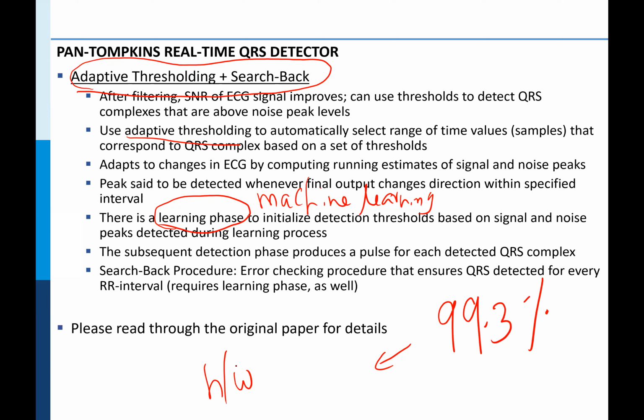Yes, they have kind of mimicked an IIR filter design, but the poles are either at the origin or on the unit circle, which is basically trying to cancel a zero there, and the effect of the pole is lost in that process.